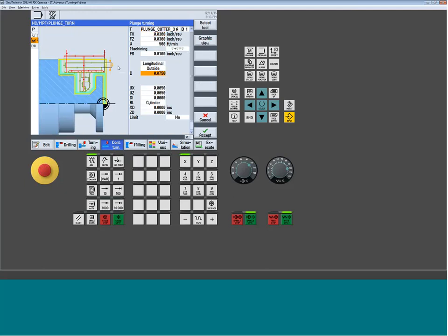The depth per pass here, that's going to be side. So this is more traditionally like a turning operation. So I'm not pecking down here. I'm actually side turning with this cutter. So a lot of times you do tend to take a little less aggressive a depth of cut with this type of tool. How much material I want to leave for a finished cut. So all this stuff's all the same like you just saw.